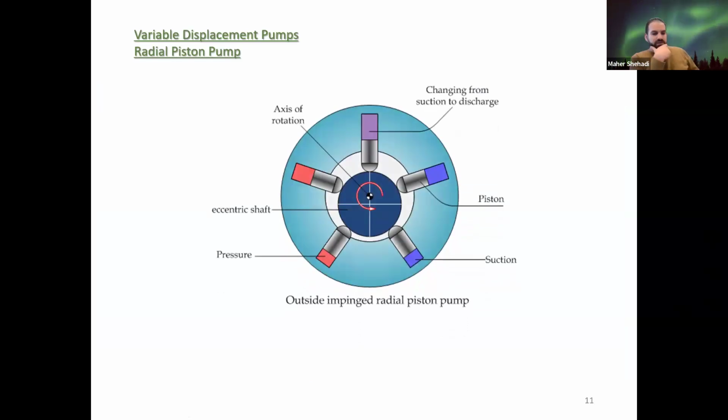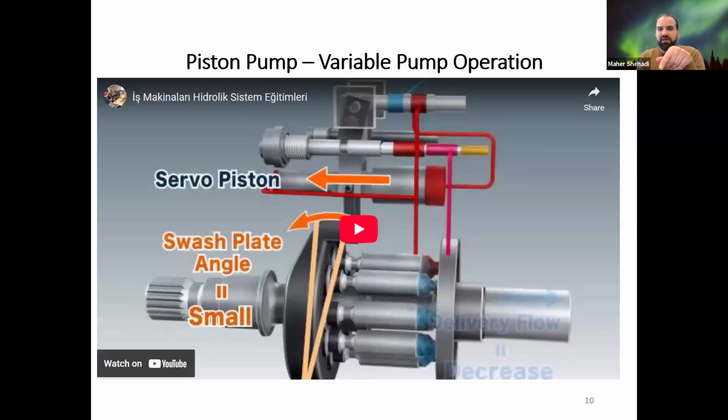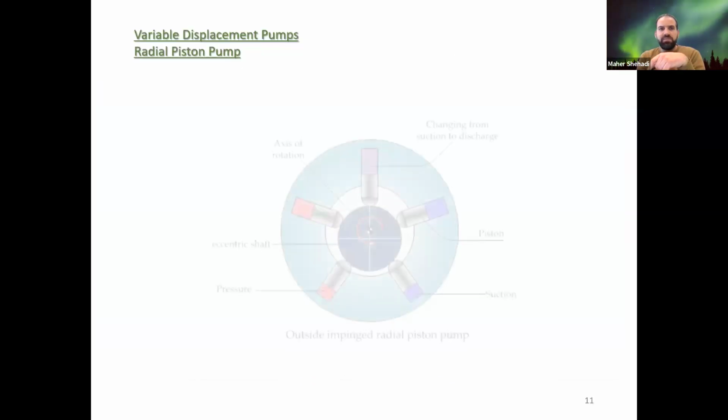All right, so now we have the third type. We checked the gear and the gerotor, that's the fourth type, or if you want, the third type is the piston pump, but now that's the radial. How we categorize these piston pumps depends on the motion of the pistons with respect to the system. We saw here that although the swash plate is rotating, the pistons, which create the change in volume, are moving axially. That's why it's called an axial piston pump.